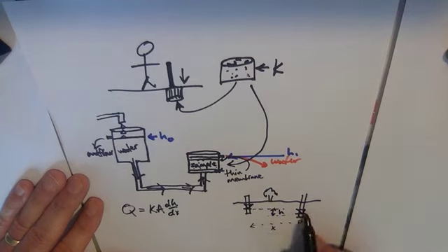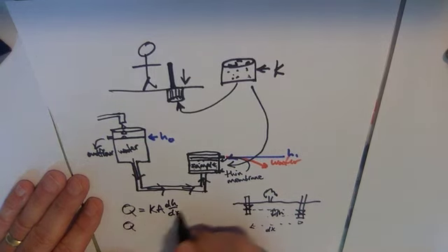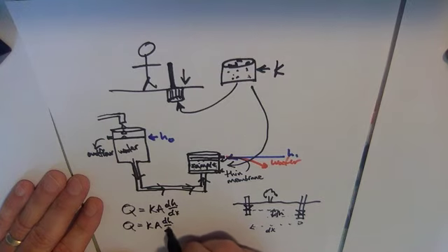And so it's the change in hydraulic head over the change in distance, dH/dx, that you use to calculate the hydraulic gradient. Now, since we're doing this in the vertical dimension, since the water's not flowing horizontally but vertically, the way this is often written is we replace x with L for some reason. So it's Q equals K A dH/dL.